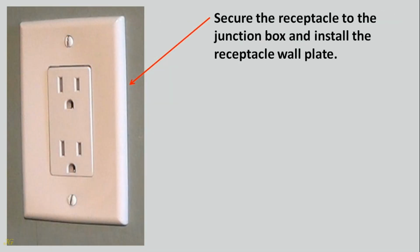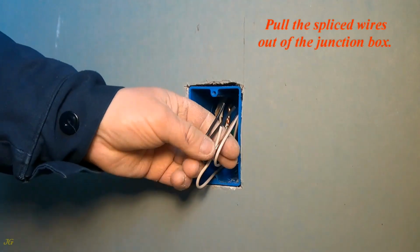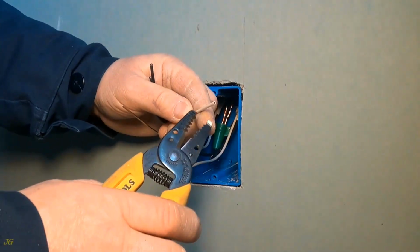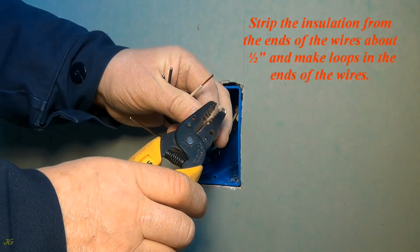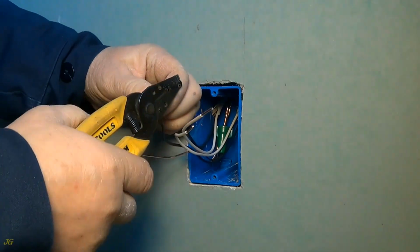Secure the receptacle to the junction box and install the receptacle wall plate. Pull the spliced wires out of the junction box. Strip the insulation from the ends of the wires about 1/2 inch and make loops in the ends of the wires.